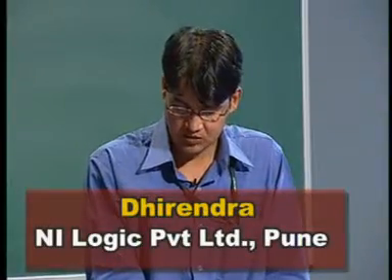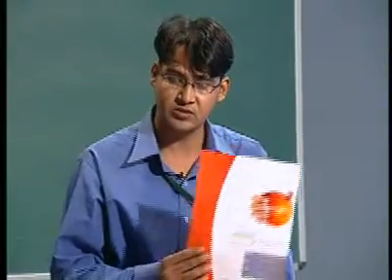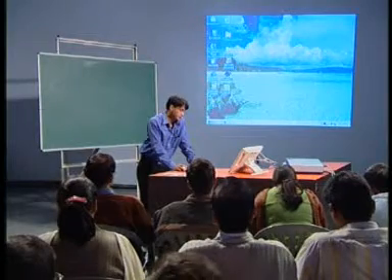Now, we will switch to this backend tool. This tool is called Microwind. This is basically a CMOS layout and simulation tool, and it has support up to 22 nanometer technology. This we call deep submicron technology, and it has support for silicon on insulator. As I already told you, silicon on insulator technology is the latest technology. We are currently working on that, so it has support for that also.